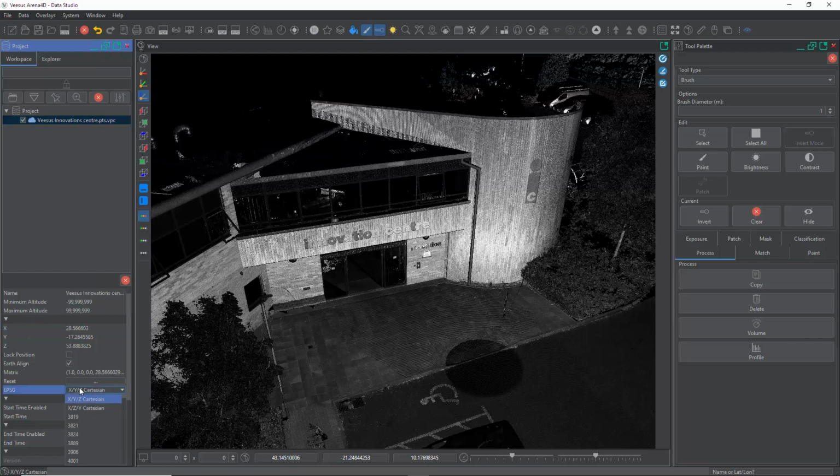So this one in particular, if you had converted your point cloud data and not selected georeferencing, and your data now just loads in this local view and it doesn't appear on the globe correctly, which it wouldn't do if you didn't select georeferencing, then you can enter the EPSG code here, and that point cloud will transition to that georeference position.